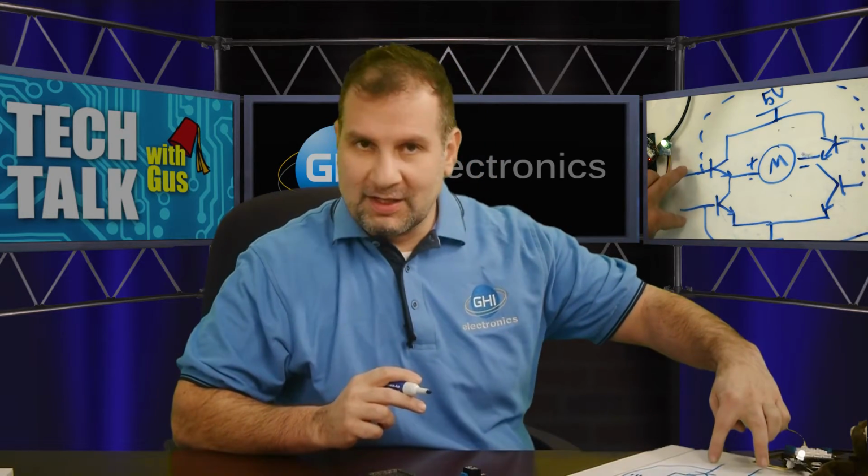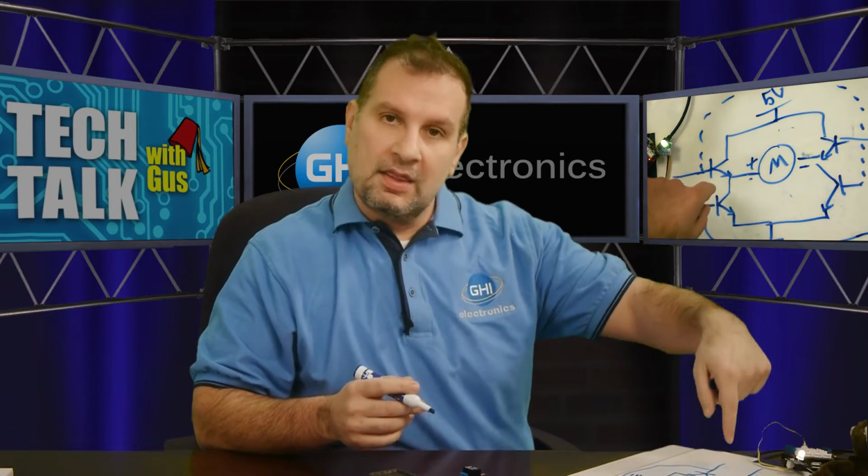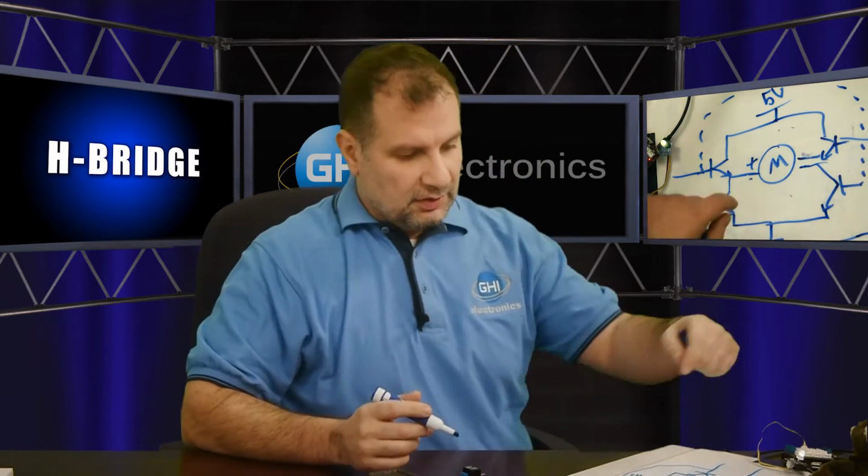Now we can't turn them on at the same time. That will blow up the circuit. So we have to be very careful here that we are turning on one at a time. Now this is called an H bridge, like a letter H. You see it here with the motor. So this is an H bridge.